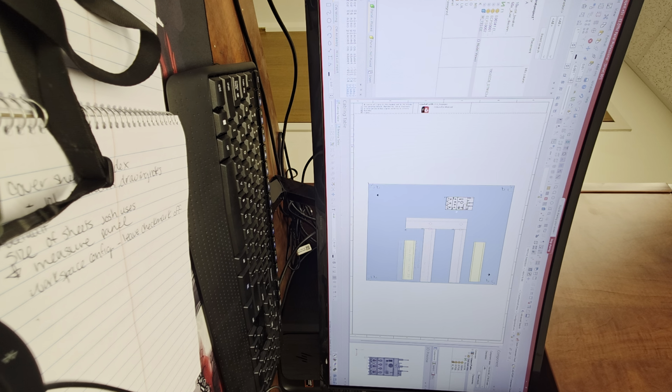So now you're fully caught up with your library synchronization, if you will. Now that part goes on the DIN rail itself. This part? Yeah. At least we added it as a TS35. The only difference is whether it actually has a space to place it on, but it looks like it does. You just squeezed it in, because if you were like 1/16 of an inch further up, the part wouldn't be able to be placed because it's colliding with the duct, right?